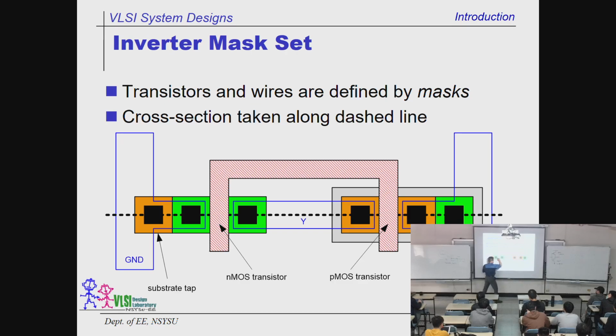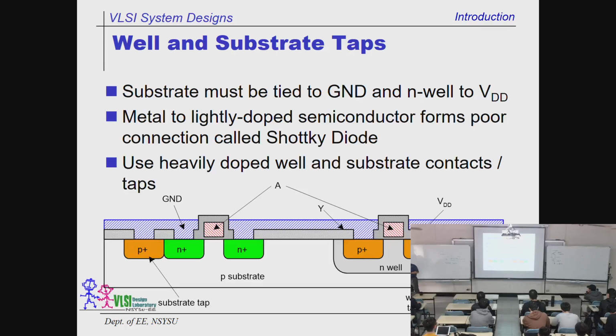Right now, we use a knife to cut this transistor, this inverter, into half. Then this is NMOS, and this is called the substrate well tap. It's over here. We're going to explain it later. And this side is ground for the NMOS, and that side is short circuit to the VDD. All right, so let's go back to the side view over here.